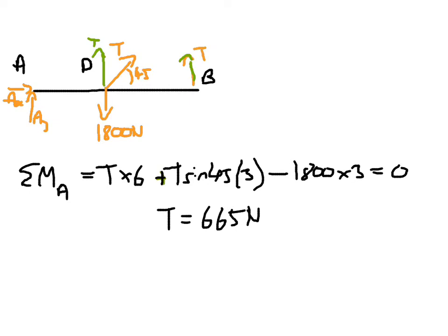Now we've found that, we can break off into half of the beam. We're actually asked for the internal forces at point F, which I haven't marked on my free body diagram, but it's halfway between D and B, so it's kind of there. That would be our point F. Now it's going to be much easier to work on section FB because we've got all the forces that are acting there. So I'll just jump to the next slide and we'll redraw that.